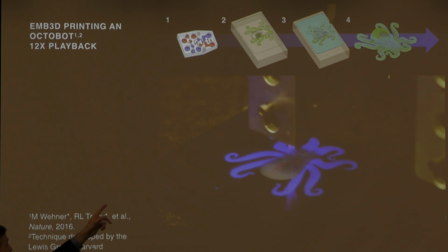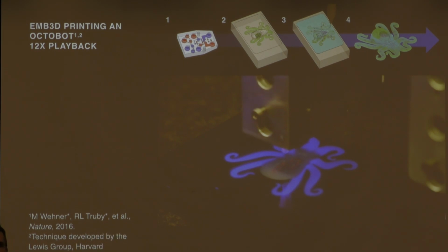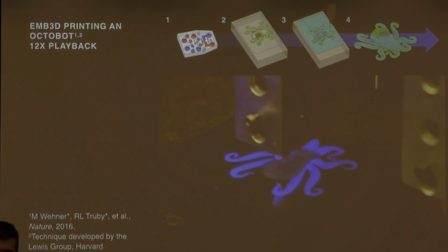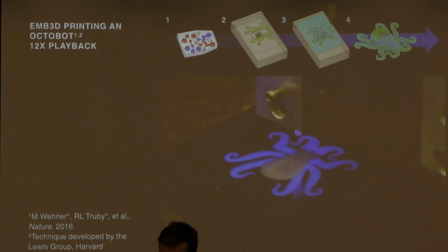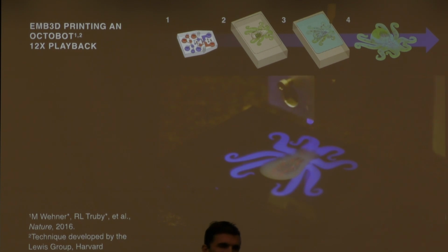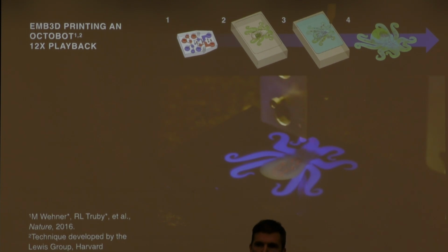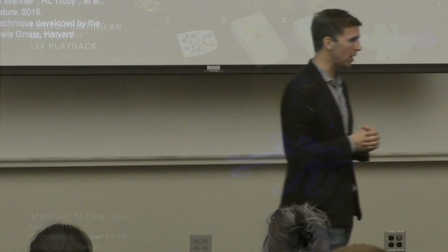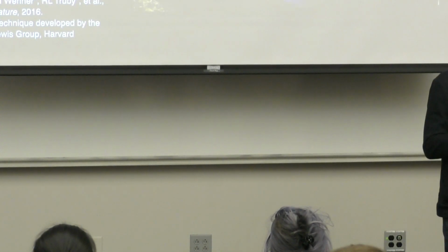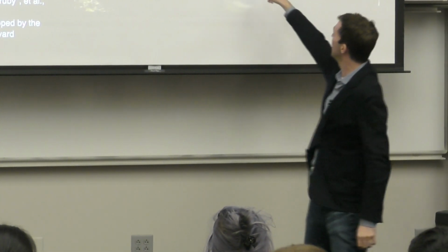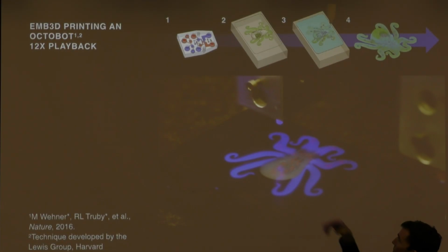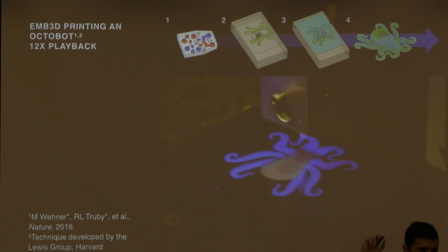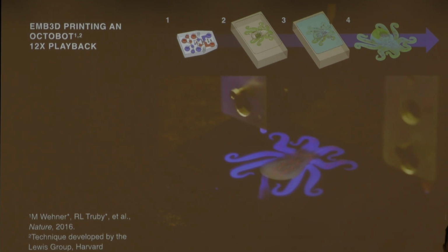And what's happening here now is the embedded 3D printing process, where I inject a sacrificial, they call it a fugitive ink. And if they get the rheologies right, and there's all sorts of magic associated with getting the rheologies correct, then that fugitive ink after printing is stable despite the fact that both the fugitive ink and the matrix are uncured. And so then I can cure the entire thing after this is done. You can kind of see what's happening here. It's dyed fluorescently so that you can visualize it. But I get the vasculature and actuation sites for this thing.